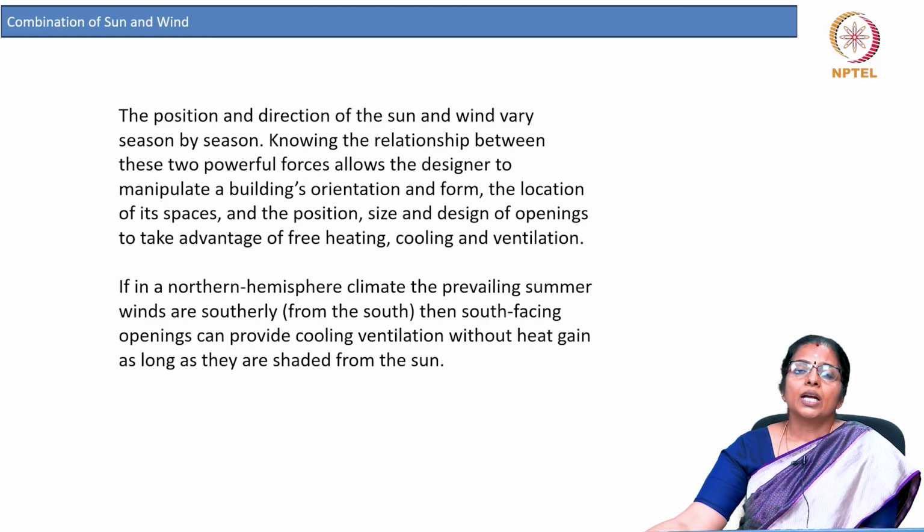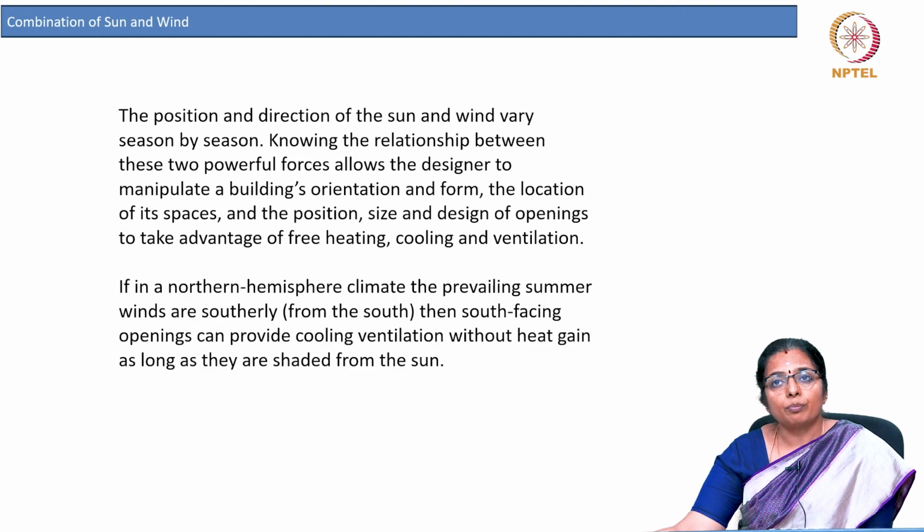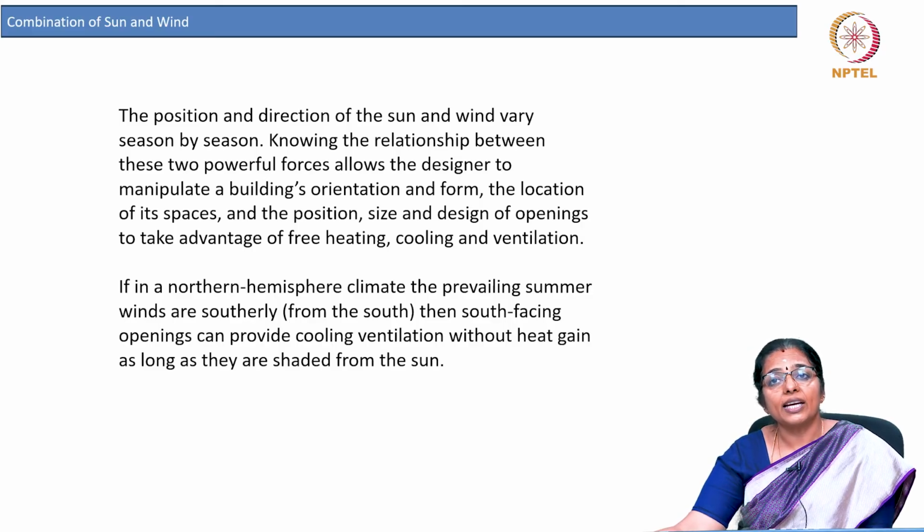Now, the position and direction of the sun and wind vary season by season. Knowing the relationship between these two powerful forces allows the designer to manipulate a building's orientation and form, the location of its spaces, and the position, size and design of openings to take advantage of free heating, cooling and ventilation.